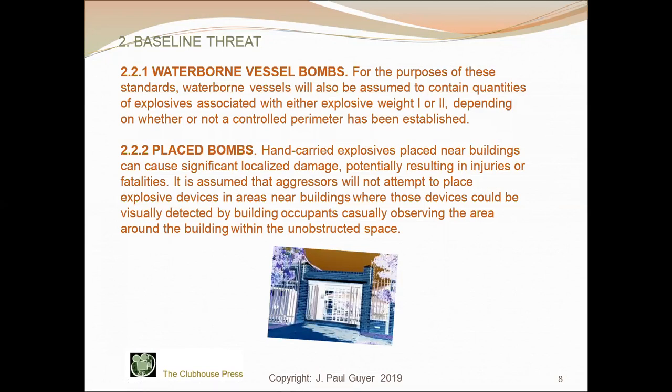That's the perimeter, how far away you keep them. And the quantity of explosives associated with explosive weights is assumed to be able to enter a controlled perimeter undetected. Therefore, the explosive weight is the basis for the standoff distances.